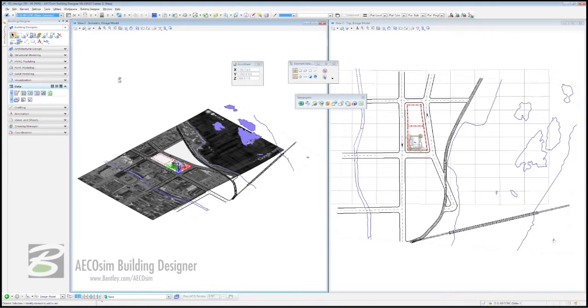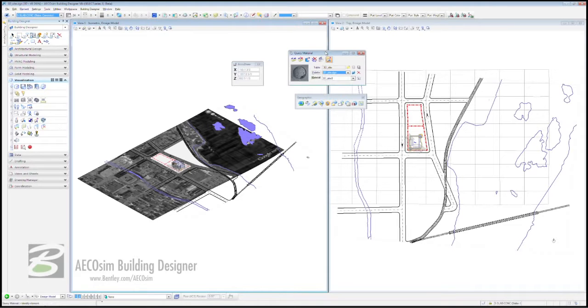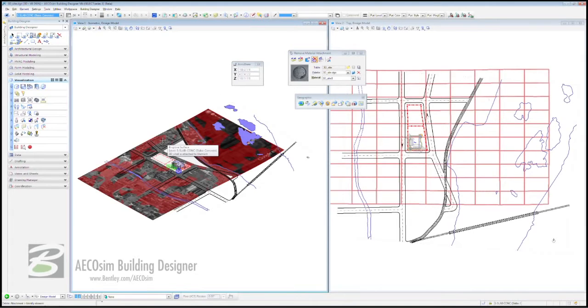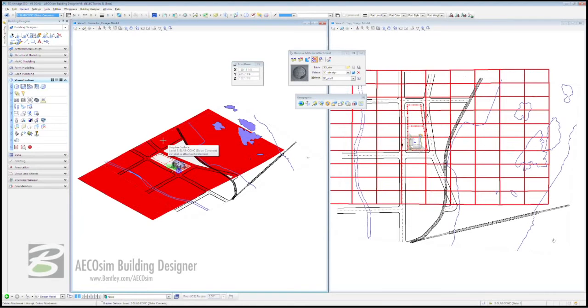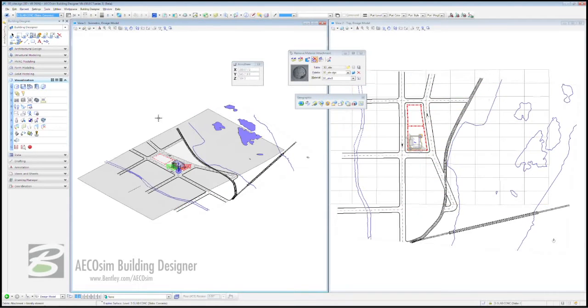We come to our task-based interface here on the left and click the visualization toolbar. If we go 6 rows down and 4 in, Query Material, and the Query Material dialog box opens, we need to actually change this. So we're going to come to the 4th icon in from the left called Remove Attachment. Select that with your left mouse button, then pass your cursor over the imagery and you'll see it highlights. Click once to select it, click again to remove it. And now the imagery has been taken away, but we still have a terrain at our fingertips.